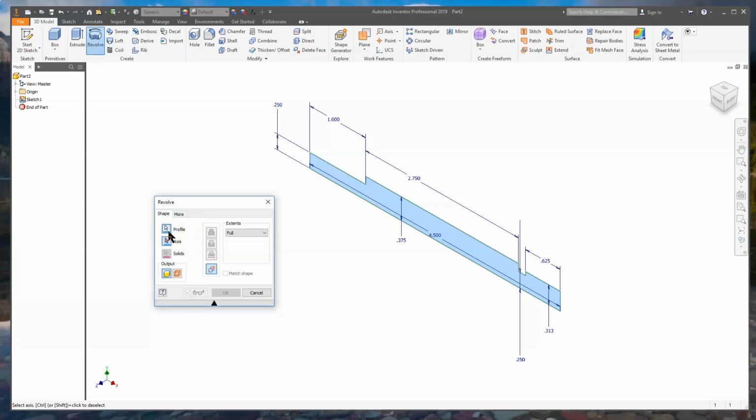All right, the profile is already selected for us. It's the only profile, and we're going to ask it to rotate it the full 360 degrees around. So this is all a good sign when it's highlighted like this, because it definitely shows us that we're closed. Now, the next thing we look at is our radius. We're going to rotate this around the center of that line. We're going to sweep it around that line. So I have to select which line I want to sweep it around.